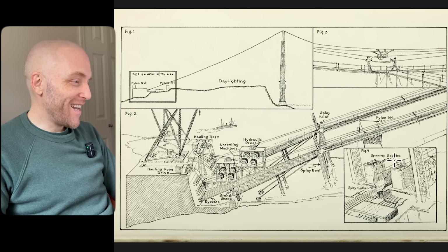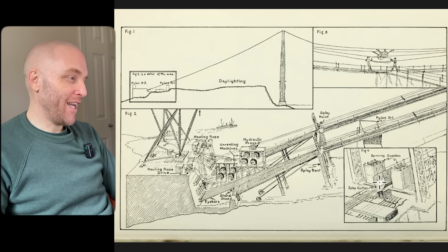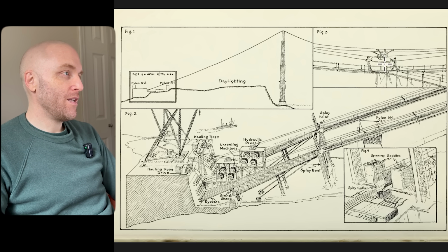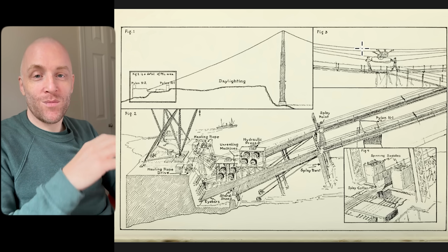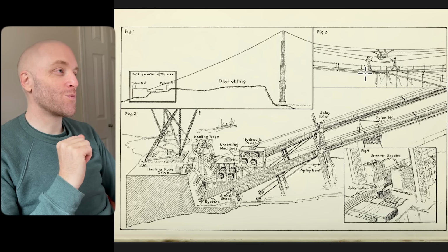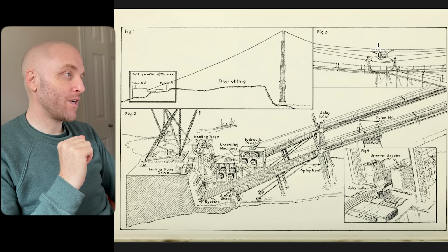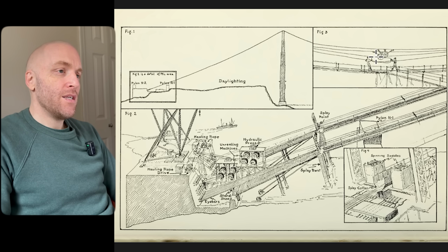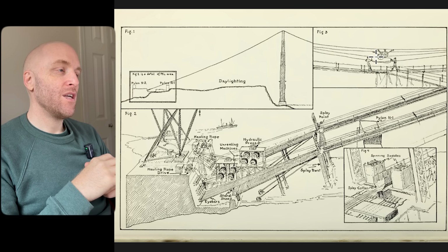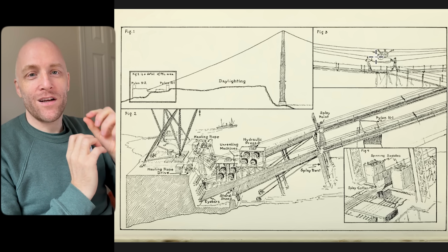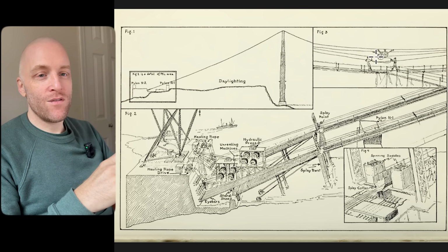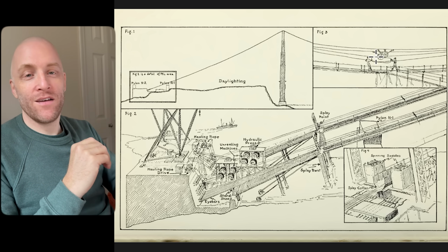The spinning saddles, which are down at that truss at the Anchorage, I did show this detail in the adjustment block underneath. Here's them switching loops, and early in the process, apparently they only had one wheel, and then they upped it to 3 wheels per carriage, 3 pulleys per carriage, but this is them switching. Some people had questions about how they switch those when it's so heavy, but when it's a single wire, it's not as heavy. And also, I didn't show this detail, but they have hooks all the way down the walkway with the rollers.